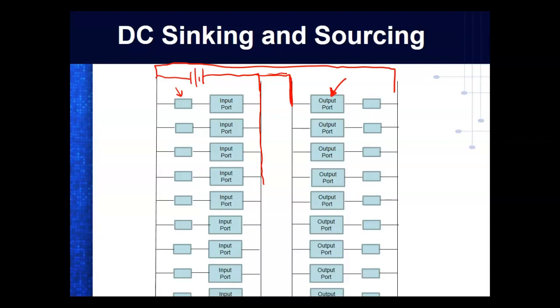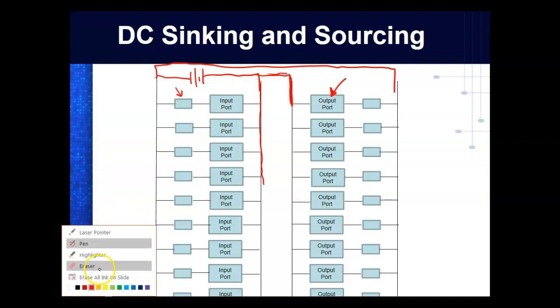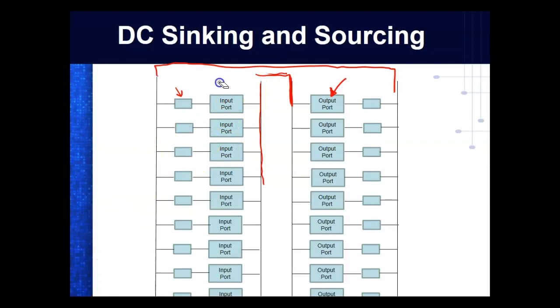Of course, what we've done is we've set ours up. No, I still have this backwards. Yeah, I got this backwards there. Nobody caught me on that. So what are we running on our PLC? We're running sinking inputs and sourcing outputs, so I'd have to draw that a little differently.